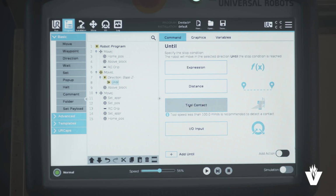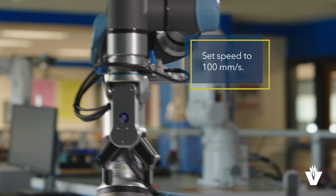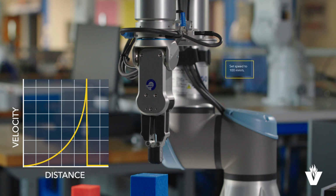Our application needs to determine the height of stacked objects, so we will use the Until Tool Contact program node. Using the Until Tool Contact program node will allow the robot to stop its motion when contact with the tool, our gripper, is established. This is why the gripper needs to be closed at the approach position. Set the speed of the linear motion to 100 millimeters per second to avoid triggering a protective stop.